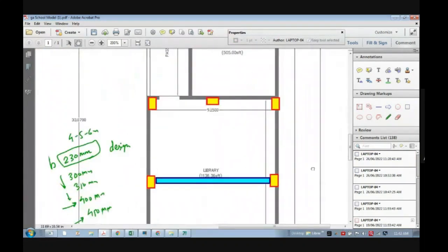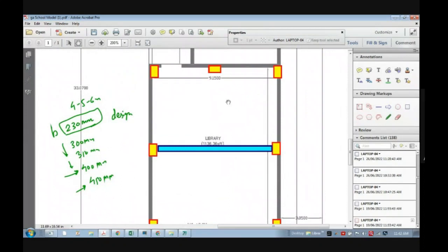Okay, so let's come back to this. Now we can provide this 9 meter beam depth. कितना लेना पड़ेगा हमें? What is your choice? L by 10 रहेगा तो it will be 900 something, isn't it? Yes, sir. So 900 mm, and you should ask the architect whether this depth is okay. Whenever you ask, you are saying that my depth requirement is this structurally. So he may say that my floor to floor height is very less and 900 mm will have a problem to me. ये बहुत ही नीचे आएगा.